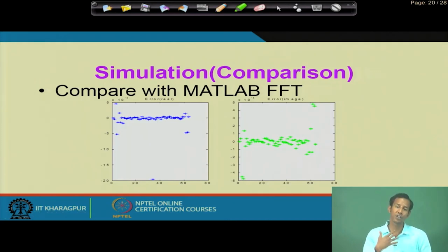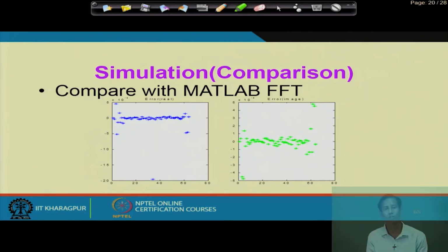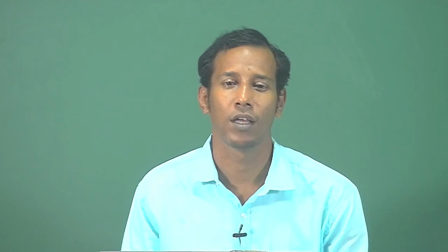So, we first run the algorithm in MATLAB to fix all these values, and then we can go for the hardware implementation using different kinds of architecture. The ultimate target for designing this FFT hardware is to use the minimum number of multipliers, minimum memory storage requirement, and minimum number of addition operations, which gives the benefit in terms of speed, power and area.